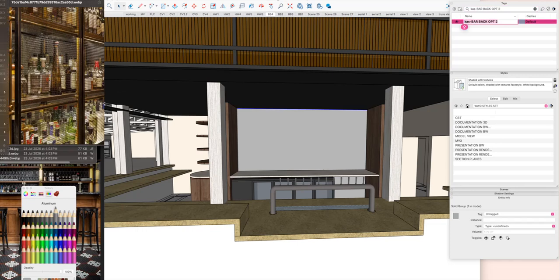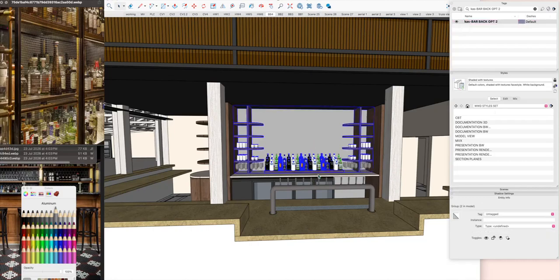I'm going to, you can't see it's not on your screen, but if you go to Edit, Paste in Place, then that brings in that copied version, which you'll notice down here is still on its untagged layer. That's the reason why I suggest you copy it whilst it's untagged, whilst you haven't put it on a specific tag yet, because then you're not going to have any problems with copying something in that's on a tag that's turned off.